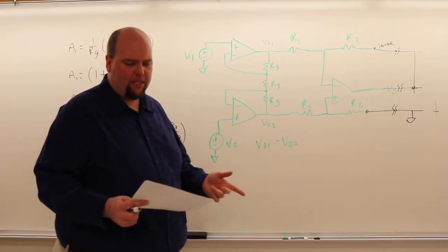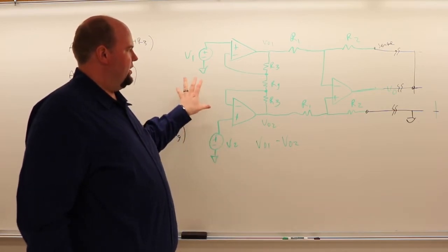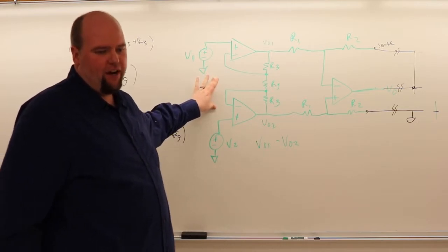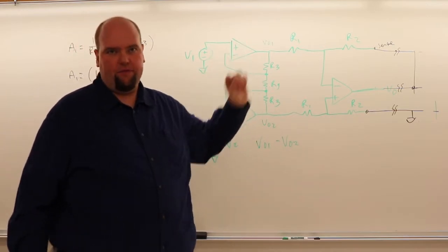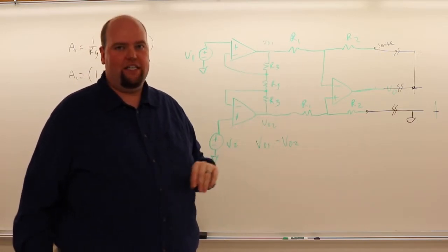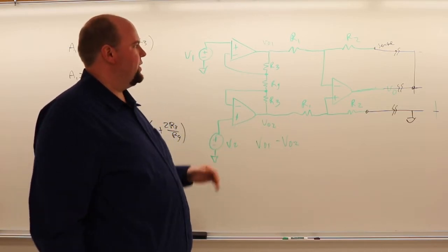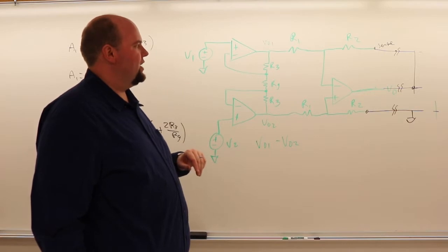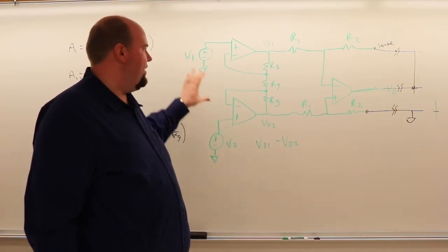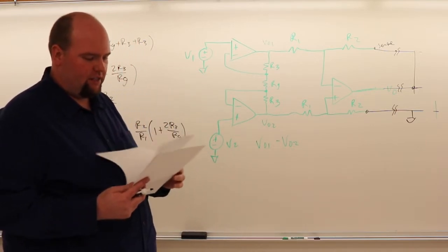We'll also talk a little bit later about ways to get a differential signal. Like let's say we had a bridge amplifier that had a differential signal that was riding on top of some noise. And let's say that signal was being transmitted over a distance and it was also picking up noise by being transmitted over a distance. There's ways we can tweak this amplifier design to essentially subtract two signals. We can subtract the noise signal and then also look at the difference here. And actually, I guess I'll jump ahead and do that really quick because it's fairly easy to do.